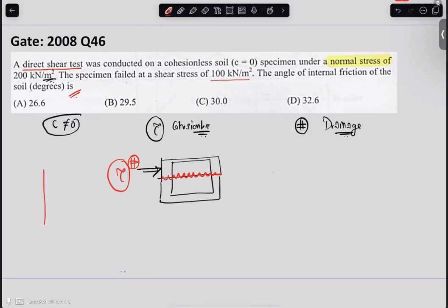You would have seen in your triaxial tests that the soil often fails like this, right? So when we are measuring the shear stress for this failure in the horizontal plane, this predefined plane, we are not actually measuring the actual shear strength of the soil. That is also the reason why we called it not a very accurate estimate, a quick and dirty estimate.